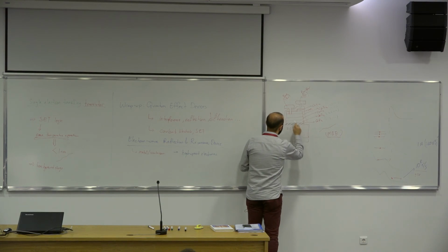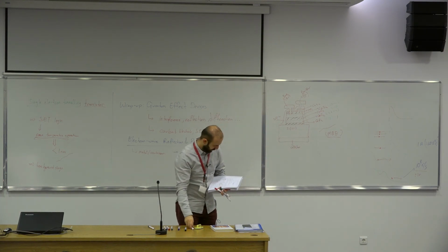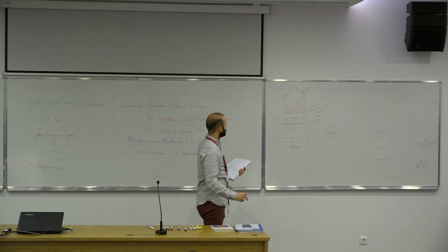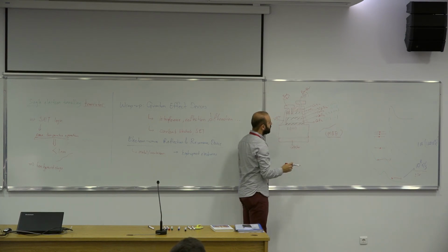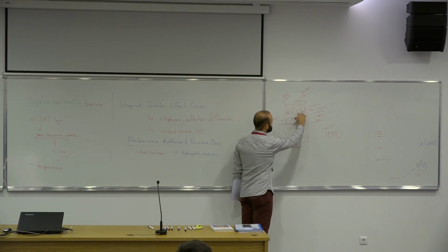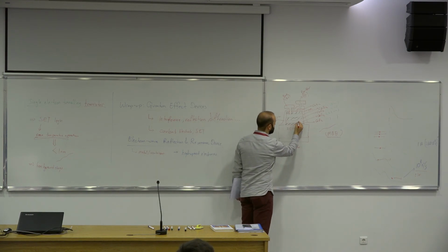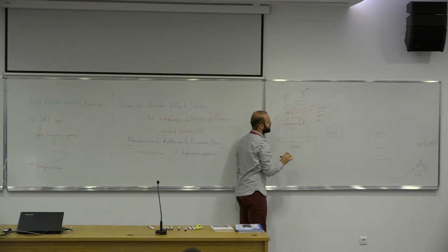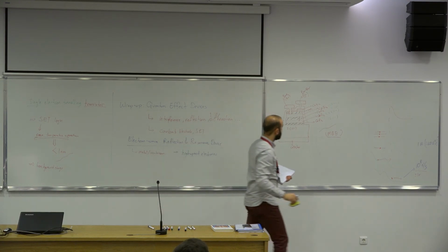These regions are insulating, okay? So the electron's motion, if you try to send an electron from collector to emitter, you need to tune the voltage, the potential, across each barrier carefully so that the electron can tunnel through these barriers in a constructive way. Let me explain what I mean.